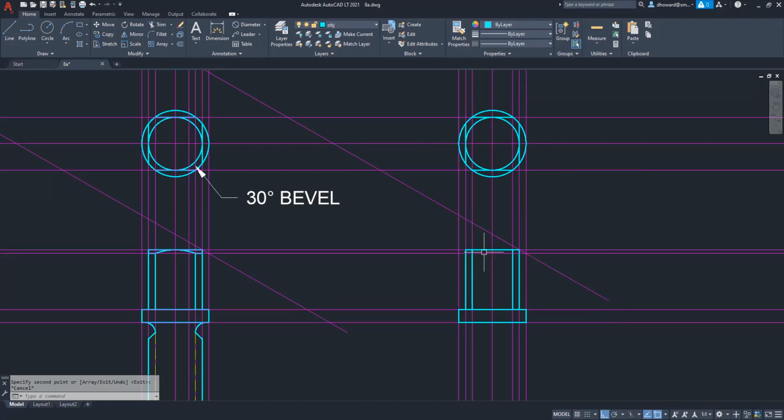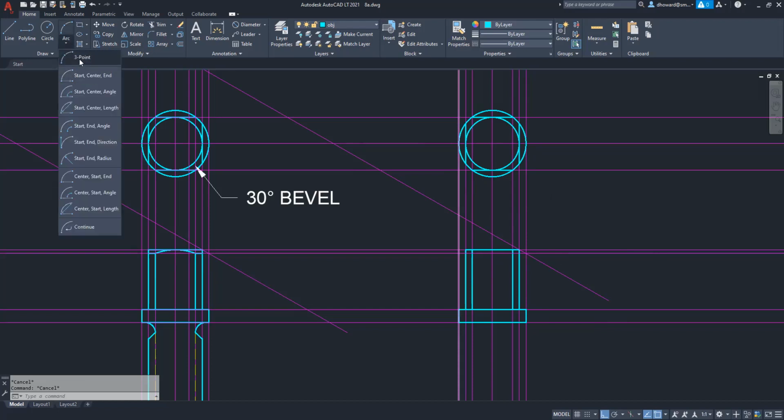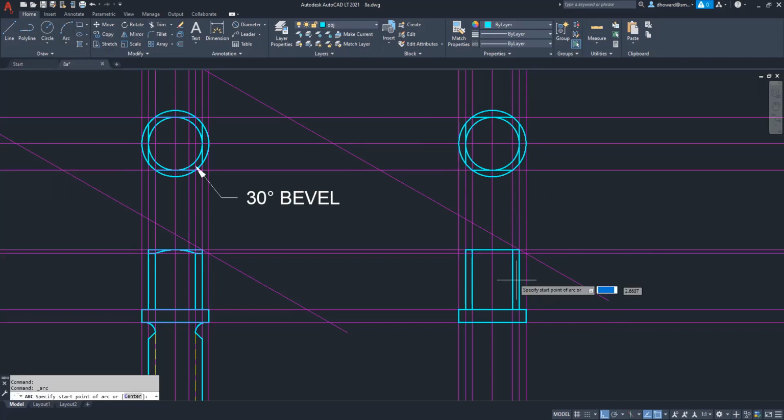Okay, and in this head-on view, we see that it creates this arc on this face. And if you look in the isometric view that they gave us, it's very evident. And that's a very realistic phenomenon. So the way to create that arc is just with the default 3-point arc, start, middle, end, right there.